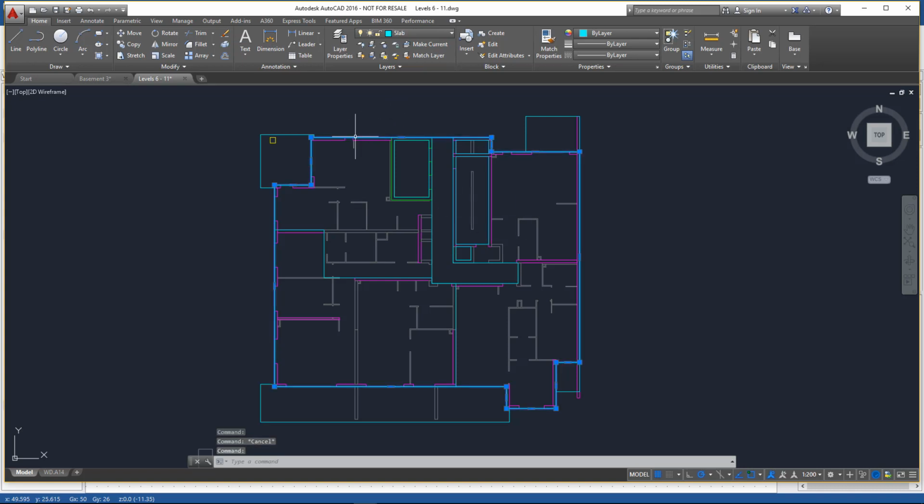But one thing that hopefully won't be an issue, but we'll see when we mesh, is that we do not have a single closed form polyline wrapping around the perimeter of the slab. So we just have one polyline wrapping around the internal area, and we have separate polyline elements around the balconies. So it might be okay, it might not. We'll find out when we import, but the best way would be to have a polyline wrapping around the entire perimeter.